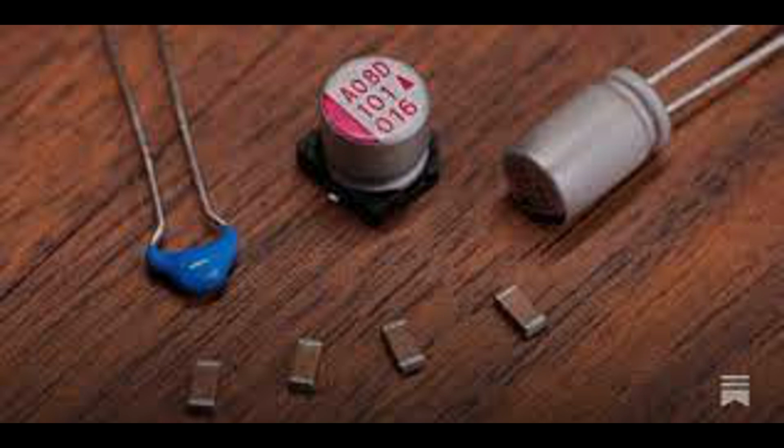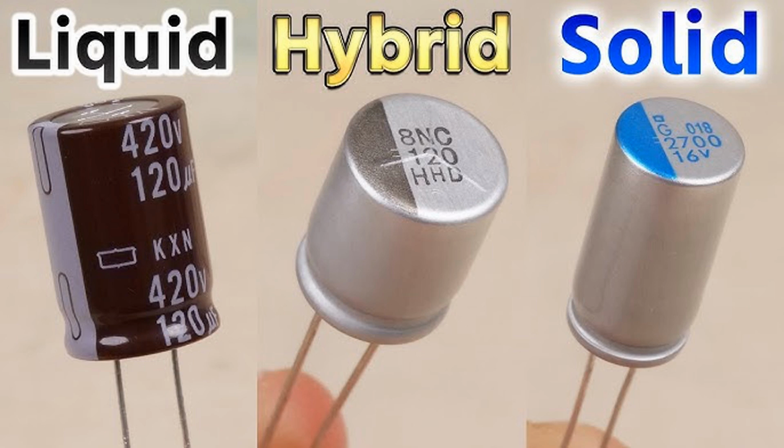Crystal oscillators. Description: capacitors are used in conjunction with crystal oscillators to fine-tune the frequency output. The crystal provides a stable reference frequency, while the capacitors adjust the final frequency. Example: in quartz crystal oscillators used in watches and precision clocks, capacitors are used to trim and stabilize the oscillation frequency.